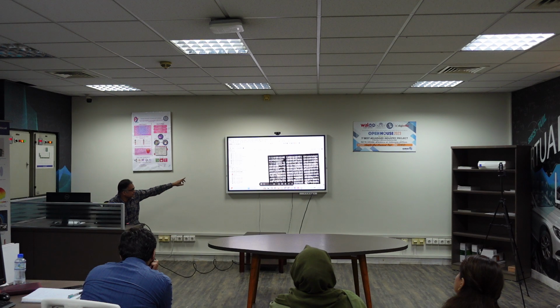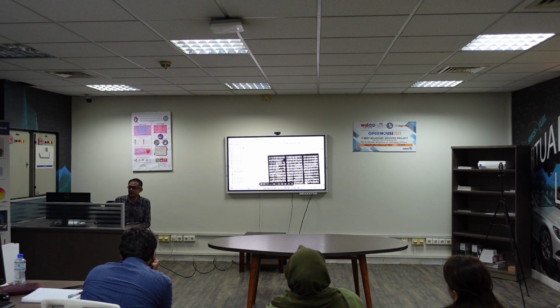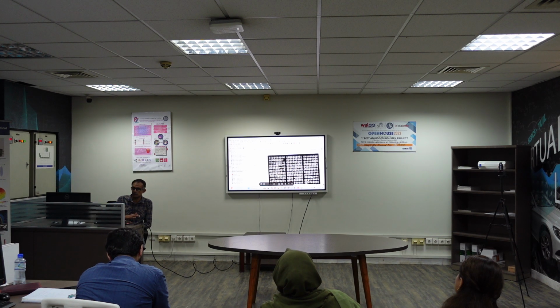However, if there are interesting features, like a board or a screen, I would immediately have a number of features from where I would be better able to distinguish between individual items. So that is very necessary during the processing pipeline of photogrammetric processing, in the initial step where we are selecting the tie points. That is why it is difficult to map flat surfaces rather than the more interesting ones.